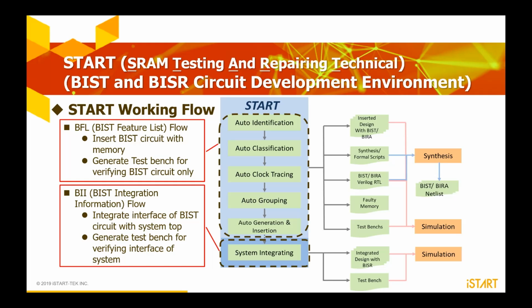After these 4 steps, we will insert our BIST circuit into the SoC design, and we also generate the test bench for our customer to verify their system design. Another flow is the BI flow. BI means BIST integration information. In this flow, we will integrate all controllers with the system top, so we only provide a single path out of your SoC chip. In the BI flow, we also generate the test bench for our customer to verify their BIST testing.